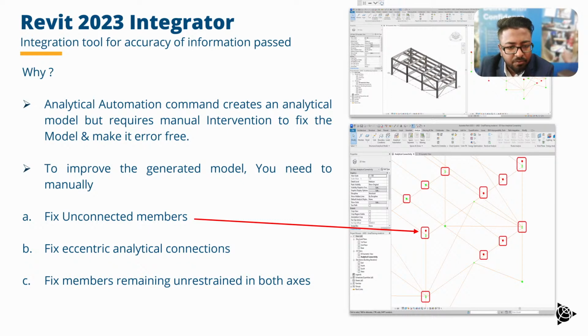So this latest release of Revit 2023 has significant changes to the analytical model in Revit. The Tekla Structural Designer plugin for Revit uses the analytical model to export the model from Revit. This release adds a tool that can automatically create an analytical model which is significantly better connected, and therefore a better model can be exported to Tekla Structural Designer than the out-of-date model that has been created by the existing feature available within the tool.